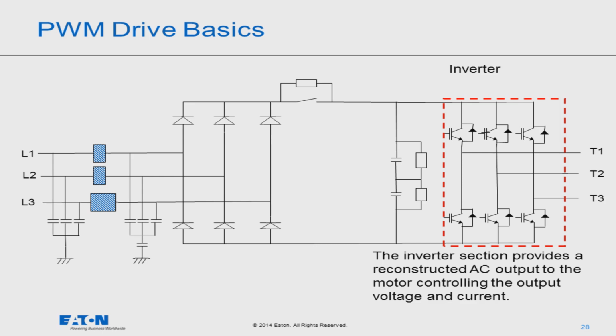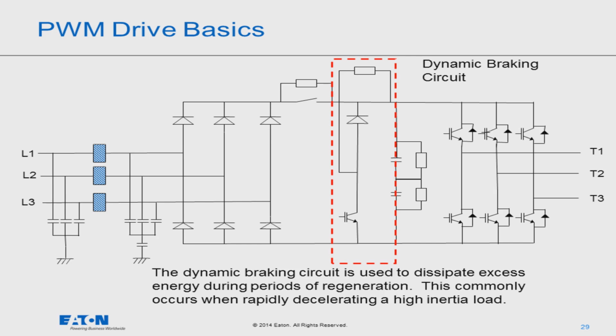The inverter is basically built with IGBTs. There are again 6 of them. The nice thing with IGBTs is that you can control both when it's open and when it's closed, and you have a higher switching frequency on them. Okay. Also, on some of the drives, on some of the smaller frame sizes, we're offering this, for example, as a standard option. On some of them, it's just an option.